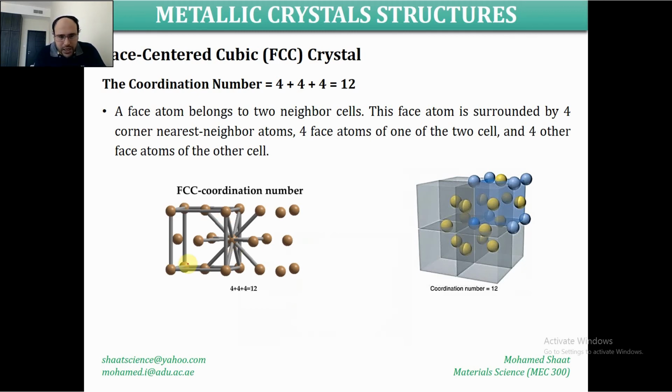Assume that this is 1 Fcc unit cell, and there is another Fcc unit cell directly next to it. There is 1 face, which is this face, that is common between these 2 side-by-side Fcc unit cells. If you choose the center atom of that face, this is the atom whose 12 other neighbor atoms you are going to count. So why are there 12?